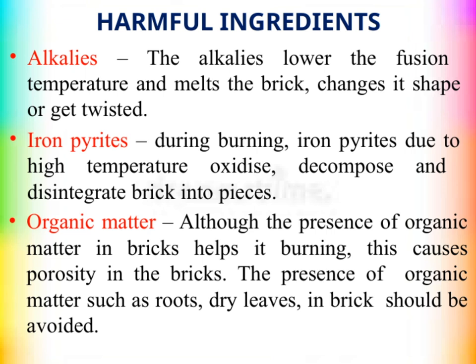Next, we have iron pyrites. During burning, iron pyrites oxidize due to the high temperatures, breaking down and decomposing. This process causes the brick to disintegrate into pieces, which obviously weakens the overall structure.